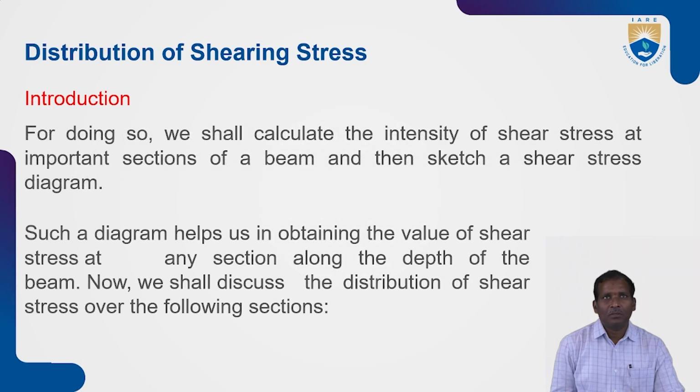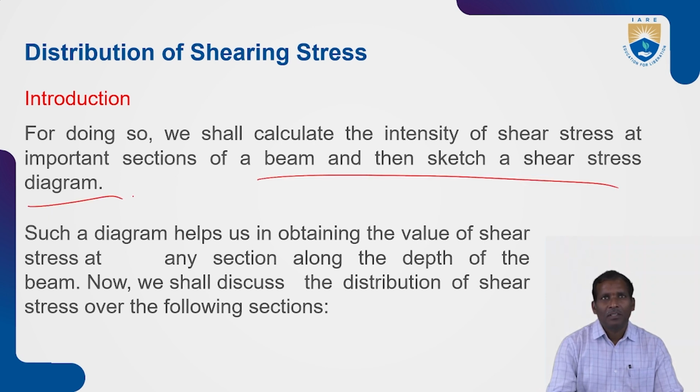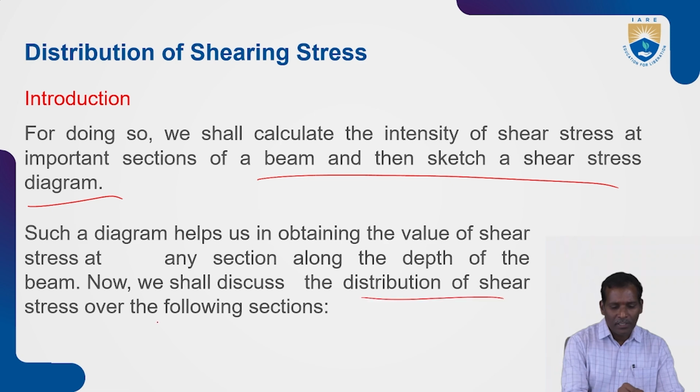For doing so, we shall calculate the intensity of shear stress at important sections of a beam and then sketch a shear stress diagram. Such a diagram helps us in obtaining the value of shear stress at any section along the depth of the beam. Now we shall discuss the distribution of shear stress over the following sections.